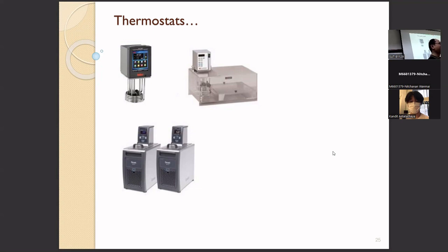But you have to check, and you have a sensor. You have the temperature from the water bath, and you have the sensor in the system. We carefully check. I do this. It's not the same. It's maybe about 1 degree Celsius, 0.5 degree Celsius different, because the reactor or vessel that you put in the water, right? The water in the water bath has to transfer the heat to the reactor, and then from the reactor to the fluid inside the reactor. That's right. It has some thermal resistance based on the reactor.